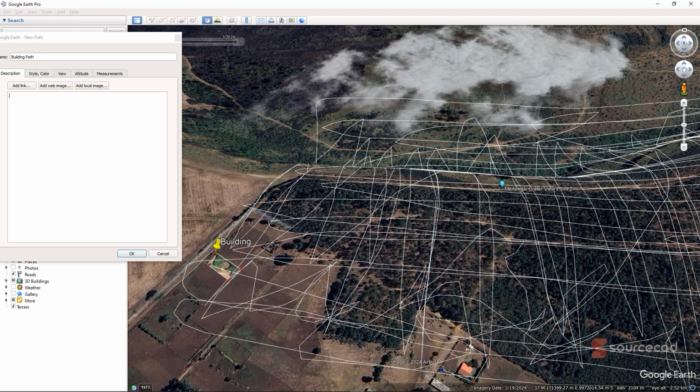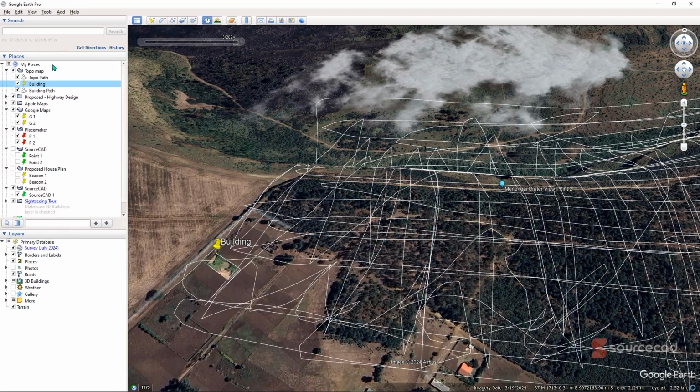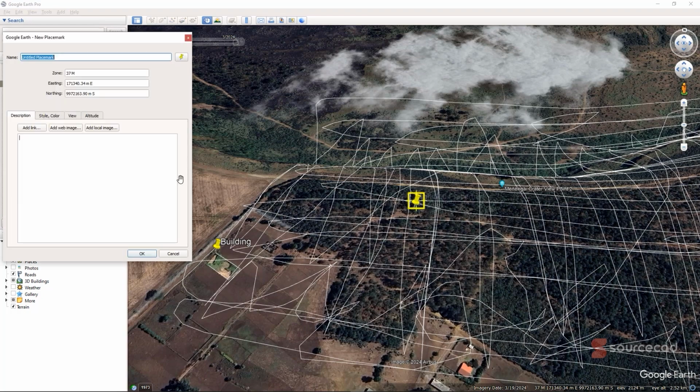But what I usually prefer is having them separate. So if I want to undo, I'll just click on my right mouse button, and just like that, it will be undone. So we can just leave it at this area. So I'll click on OK. Then I can create other place markers in this situation so that we can have multiple place markers.